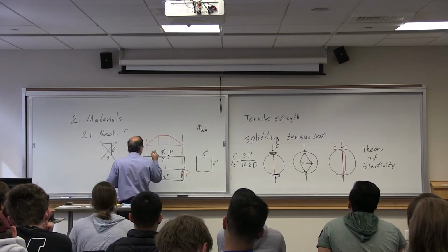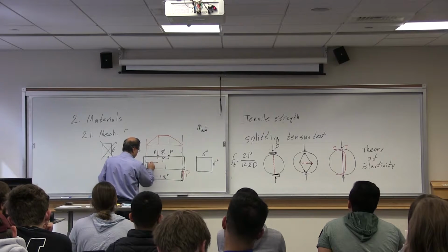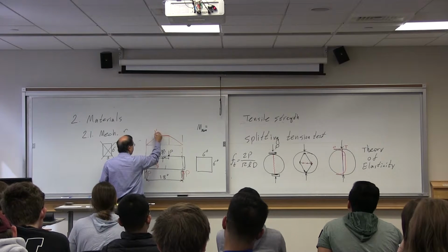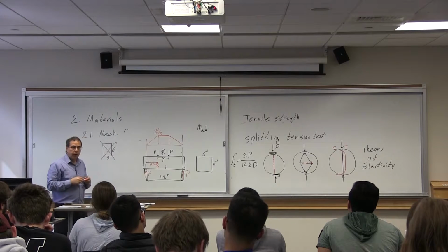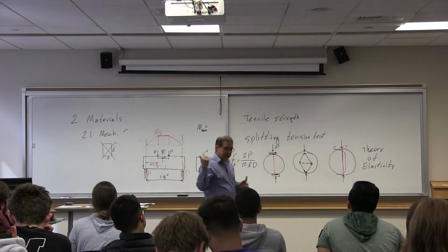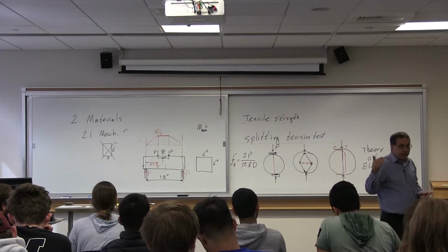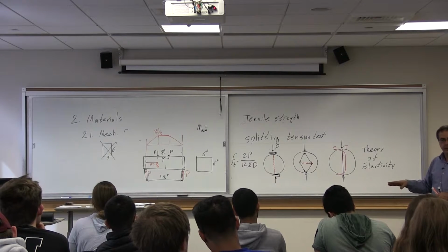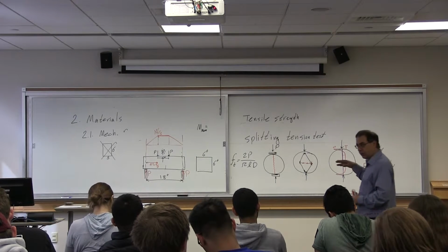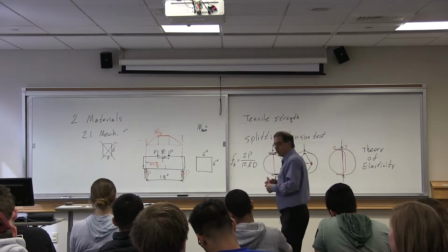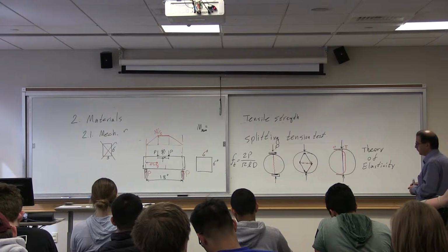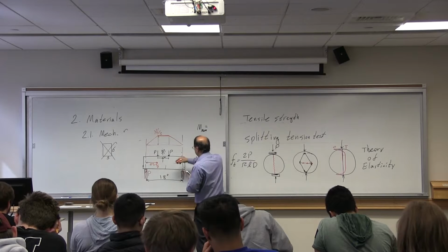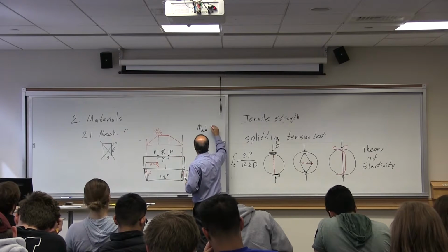So what we have here is this length is 6 inches, which is L divided by 3, PL over 3. Consider this: if you know this, the better. If it's not clear to you, that's kind of the lowest bar of statics. We will need much more than this knowledge of statics, fresh, that you can use to solve problems. So, therefore, the maximum moment in this case, if this is 6 inches, would be 6P.